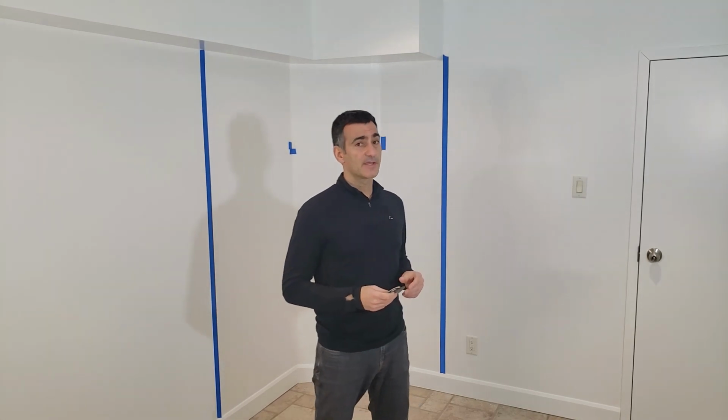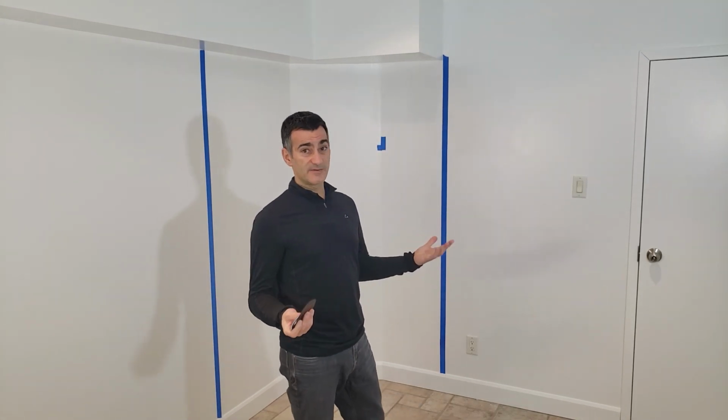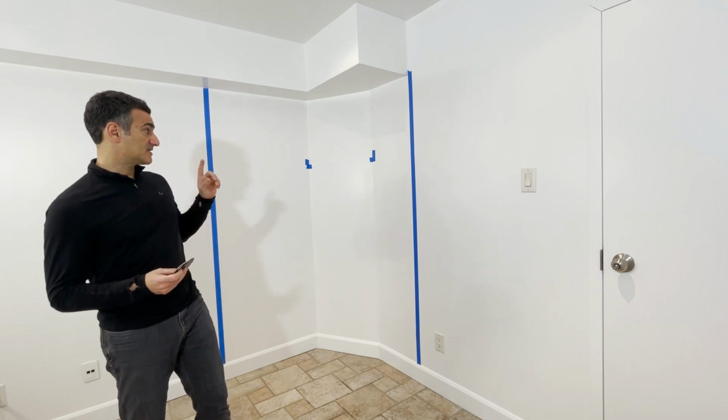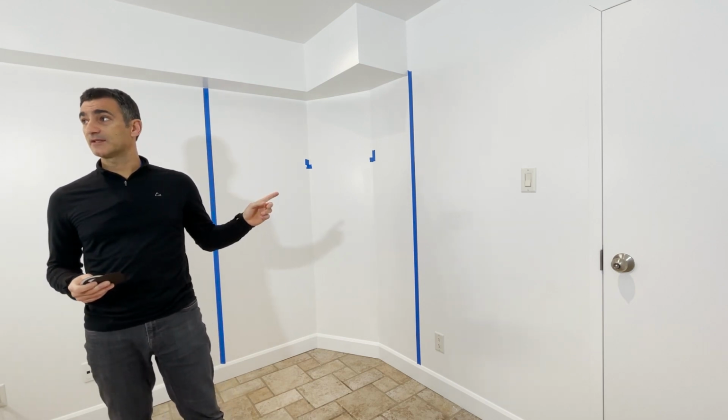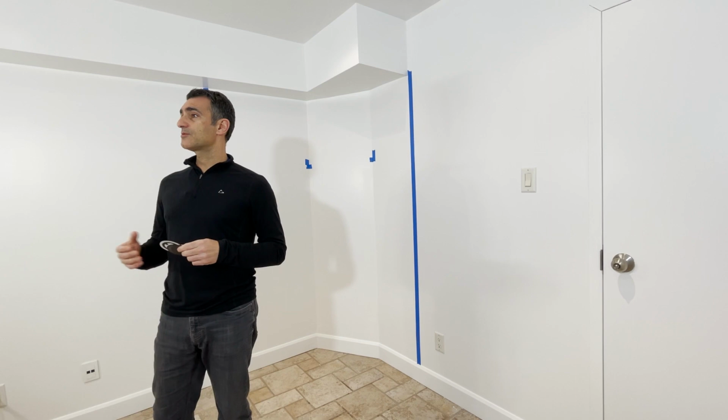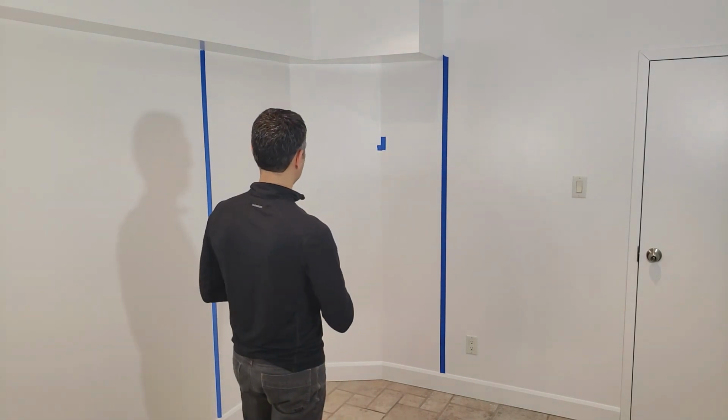This is the program where we talk about photogrammetry and how you can use your digital camera to create 3D models. Now today I'm going to be trying something that may sound very simple, but it's creating a model of these walls back here. If you're using a program like Metashape or 3ds Zephyr and you're using the automatic reconstruction to make a point cloud and then a mesh, this is actually an extremely challenging project, and it may not seem like it because it seems like something very simple.